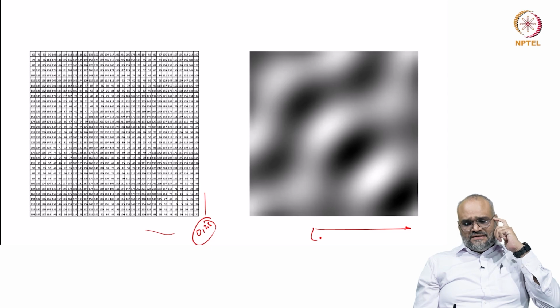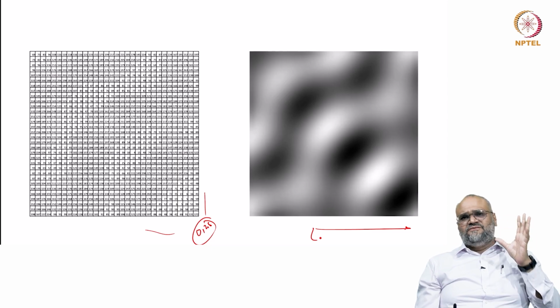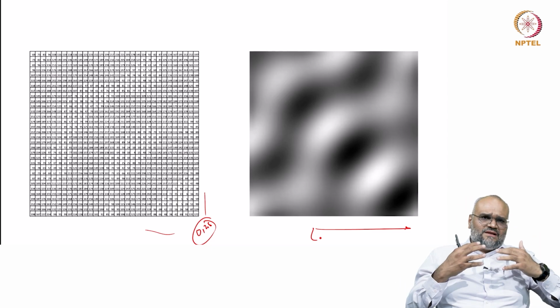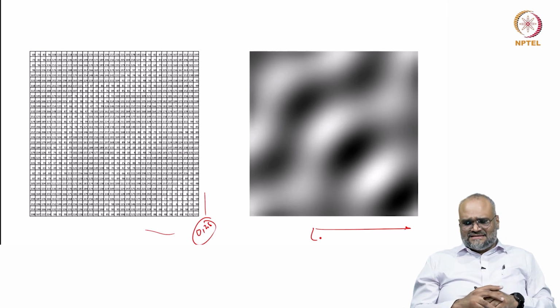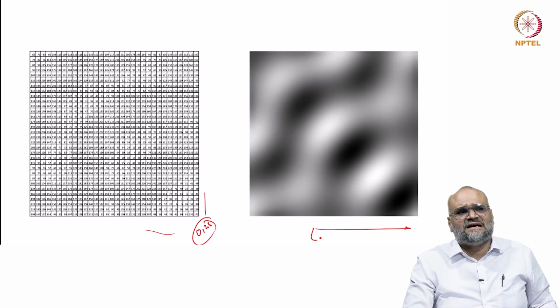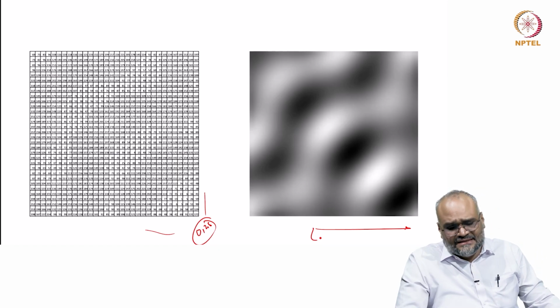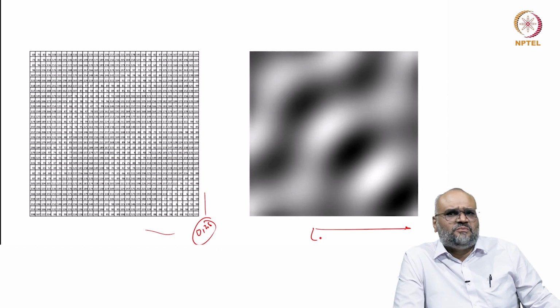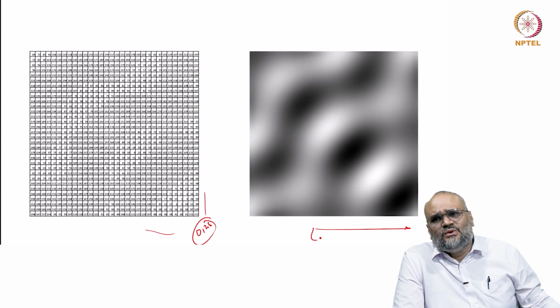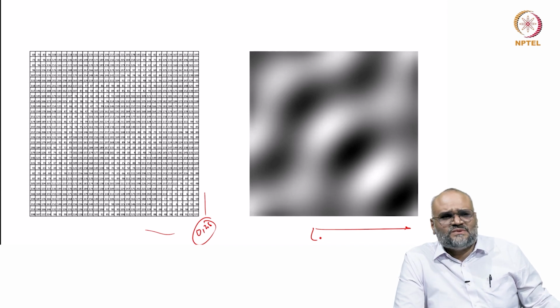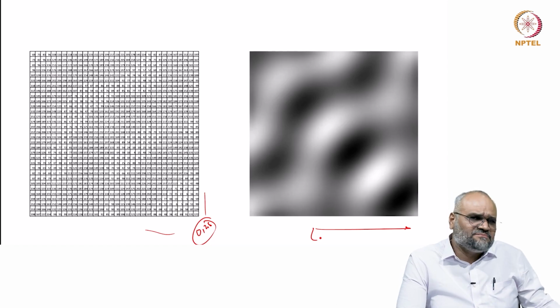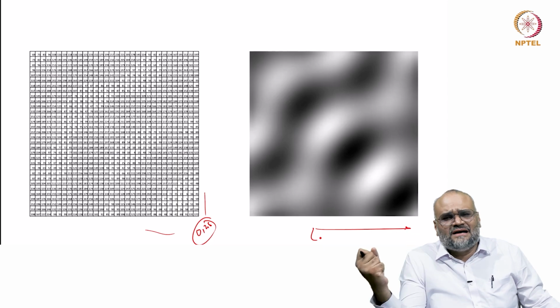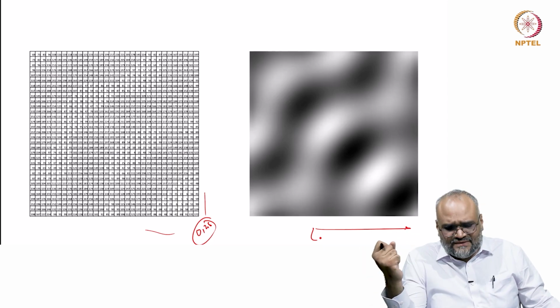So remember, there is definitely some information regarding the material which you are trying to retrieve and correlate, but the imaging system that is used is displaying only intensity variations which are captured on a fluorescent screen or a CCD camera. And when it is this kind of a process, there can be artifacts which can often be misleading, and before you interpret the intensity variations with some kind of microstructural features, please try to understand why this intensity distribution happens and then correlate it with the knowledge you have on the material. That is when you can do a comprehensive analysis.